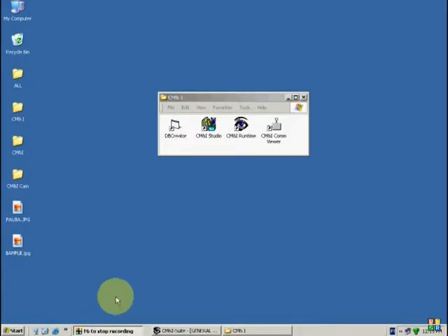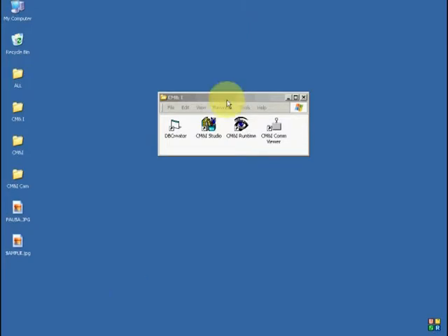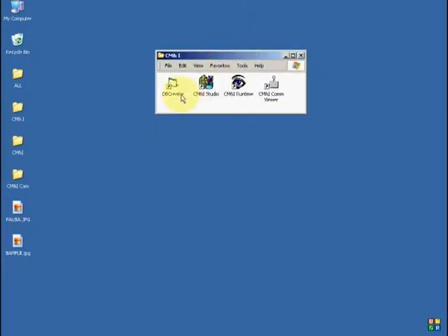The CMI suite is a SCADA software composed basically by 4 modules. The DB Creator that reads a JTX file and creates the application database. The CMI Studio that concludes the database generation, creating the screens of the man-machine interface. The CMI Runtime, which is the program that monitors the panel by itself. The CMI COM Viewer that is used as a communication support tool.